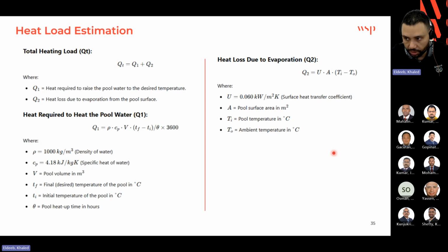Usually the HVAC designers, if we have an HVAC designer here with us, consider the air temperature in their design slightly higher than the pool temperature to minimize the condensation. So if we have a pool temperature of 28, they do their calculation based on 29 or 28, but not lower than this, because if it is lower, it keeps evaporating, and over time you will find the whole room filled with fog and condensation. Okay, so you can apply this here.